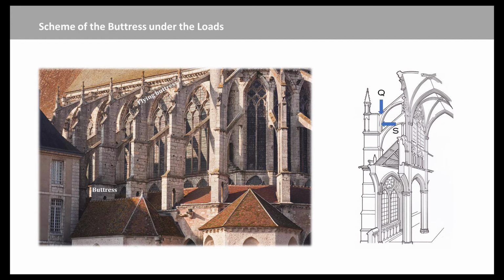In the next, the limited thrust producing the overturning of the buttress will be obtained. The vertical load applied to the buttress will be the weight G and the vertical load V. The thrust will be considered affected by the lambda. The activating of the overturning mechanism will be accompanied by the formation of a detachment fissure starting from the base